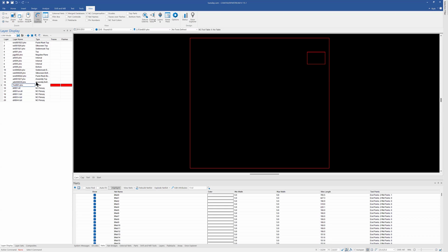It's actually the center of this line that we drew over in our CAD system. So to really get the exact board edge straight for analysis, step and repeat, whatever we want to do, we used to run a little utility called draw to one-up border, and it would make the software recognize the center of this line to be the board edge. Well, with this release, we did add a shortcut to that.